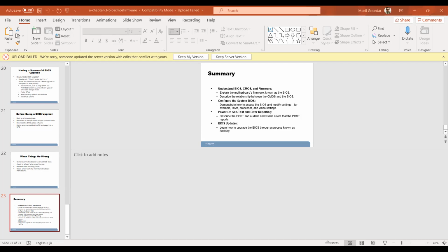Push the module straight down into position. A slight rocking motion from end to end helps seat stubborn modules into the slot. Engaging the locks requires extra firmness to force the locks to close into the notches on the sides of the module.